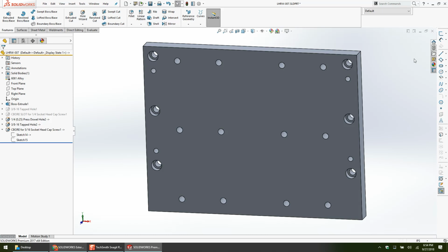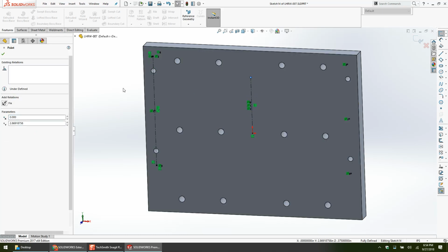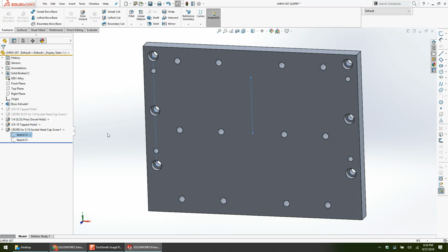Question, superficial, but do you leave your mirror lines undefined in the length? Yep. I used to define the length of them until SOLIDWORKS got smart and didn't undefine the sketch because of one construction line that didn't have 1 point. Prior to 2014-15, if you had a point that was undefined, there was a minus sign in the sketch. Like when I grade homework, if there's a minus sign, people get points off. I don't even open the sketch.